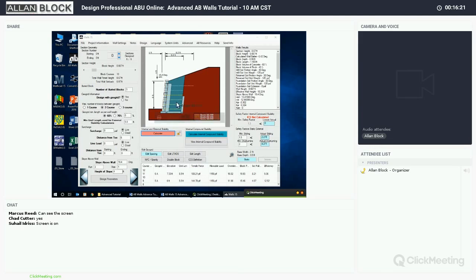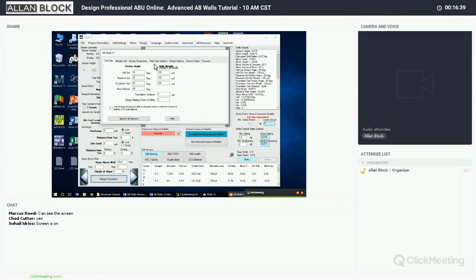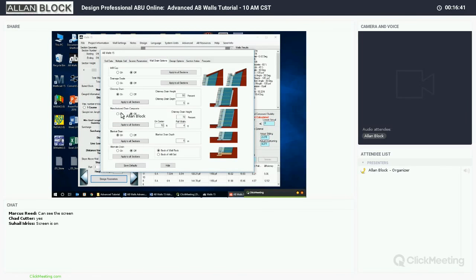We know we've got a lot of producing partners and some industry experts out there that love using a geocomposite or some type of a geotextile at the back of the cut. Makes it easier for installation, makes it easy for that management of that material. And so that's pretty simple too. We brought that in based on different requests. So instead of the chimney drain, as soon as I click the composite drain, you'll notice that it automatically toggles the chimney drain for the rock off, so we're not going to use both. It doesn't matter.